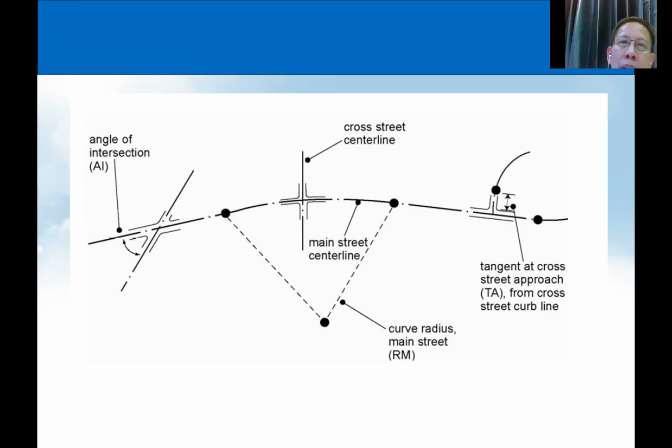In this case it is going to be challenging because you will see the possibility of more accidents rather than making it safe. So to avoid that, if it's unavoidable, for example, one may consider doing a tunnel, or doing a grade separation for the minor street.